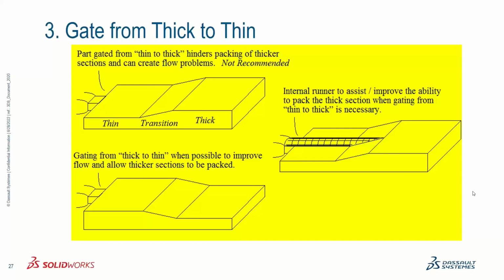Ideally, when it comes to this particular design, perhaps the best scenario would be to try and core out the thick section if possible, such that you have a uniform wall thickness throughout the part, so you don't have this thick, thin region situation.